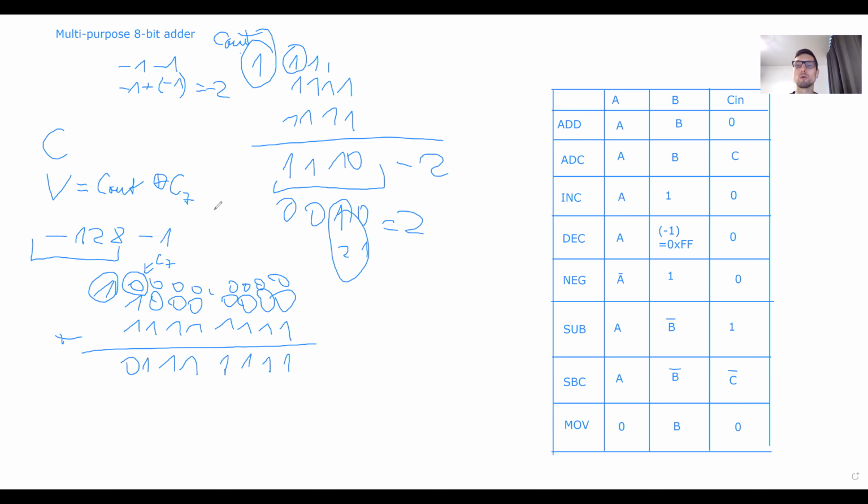Well, of course, you should always write a code that doesn't have overflows, because you write C programming. In C programming language, you don't really work with these status registers. This is maybe a little bit from older days, but generally, V signed overflow flag is there, and it can be also sometimes used for some comparisons or for some branches. But generally, this is what you can remember if you want to. And you will actually build it in labs, so you'll remember it. So carry flag is overflow, V flag is signed overflow. If you are adding two negative numbers, you need to check it instead of carry.